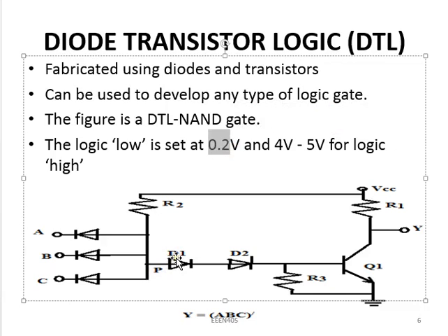But this diode requires 0.7 to conduct. This one also requires 0.7 to conduct. Then between the base and the emitter of this transistor is also another PN junction diode. Therefore you need 0.7, 0.7 and another 0.7, making it 2.1 volts minimum for this transistor to start conducting.